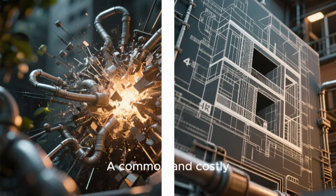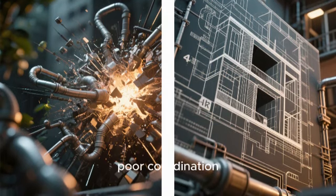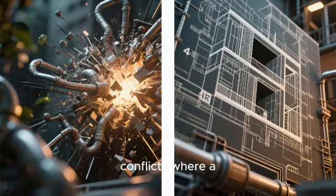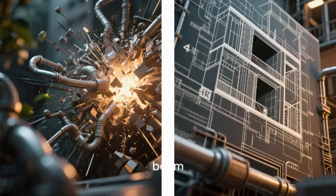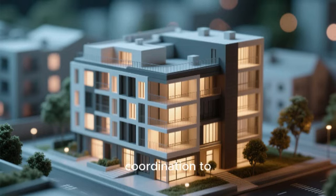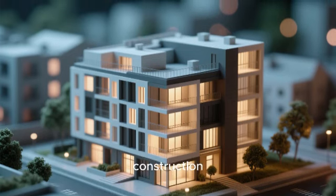A common and costly drafting mistake is poor coordination between architectural and MEP drawings, leading to conflicts where a pipe must run through a critical beam. A pro tip is to use BIM for 3D coordination to clash detect these issues before construction.